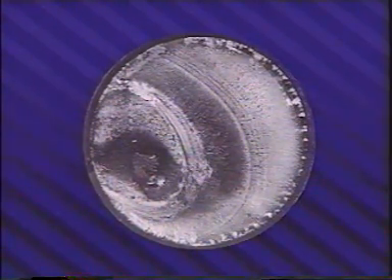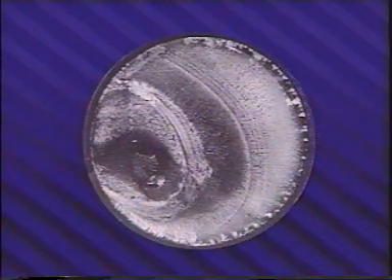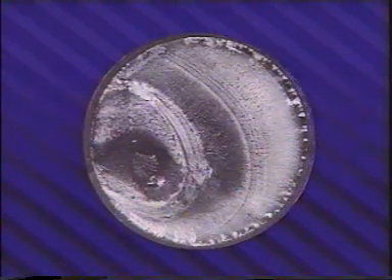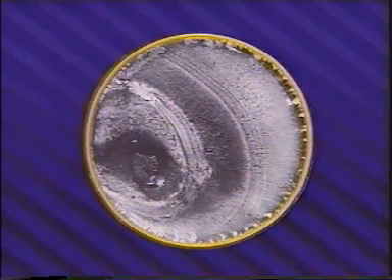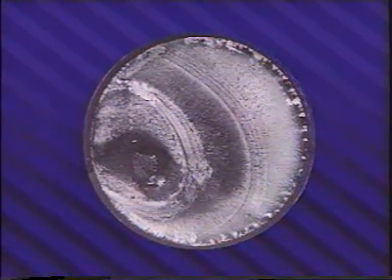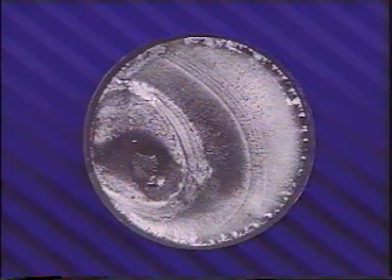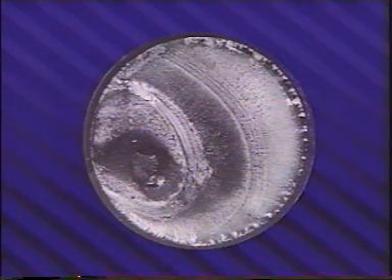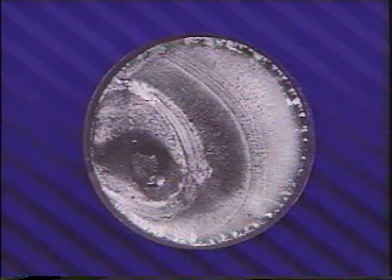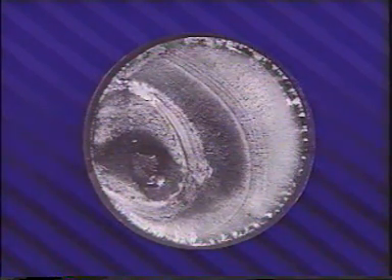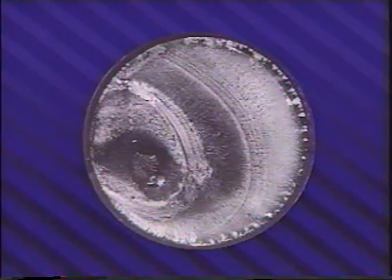In this tractor power takeoff shaft, beach marks appear over a large portion of the surface. The fatigue fracture initiated in the sharp corner of a snap ring groove. Ratchet marks around the shaft periphery indicate a high stress concentration, but a low overstress. The original sharp points of the ratchet marks were damaged after the fracture by contact with the ratchet marks of the mating surface. No fatigue origins appeared on the upper left side of the shaft.